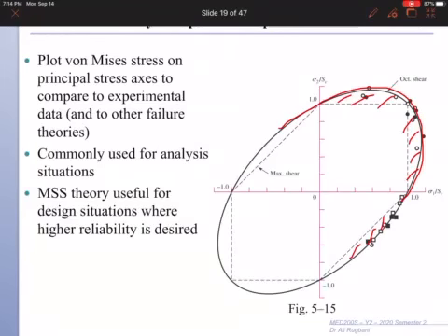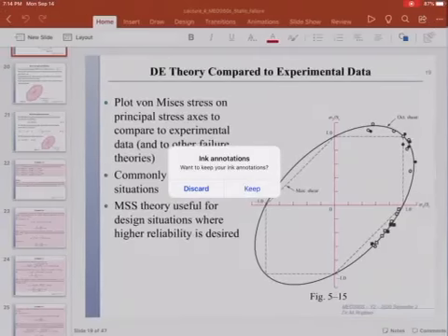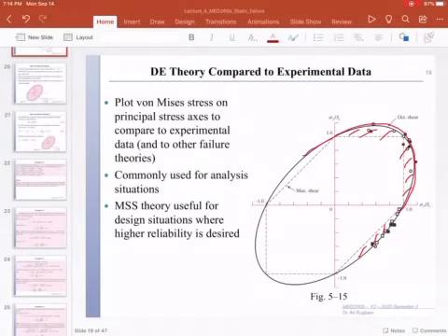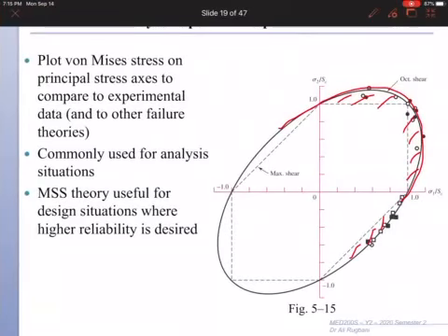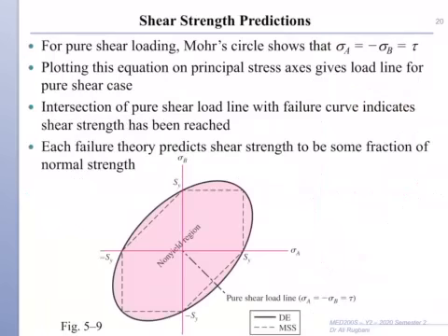If you need accurate results with a low factor of safety, then use distortion energy theory. You can use maximum shear stress theory for situations where reliability is not critical, for a rough estimate, and when you don't need agreement with your experimental results.